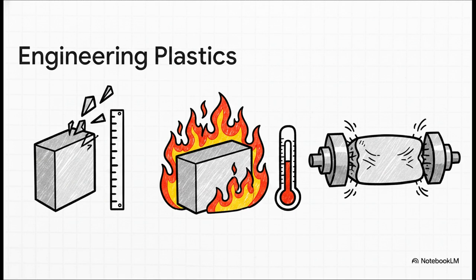And then there's PTFE, or Teflon. It's incredibly chemically inert, sure, but it is so soft that operators have to be extremely careful just chucking it into the machine. I mean, they literally risk crushing the part before it's even cut. No way around it. You have to be gentle.